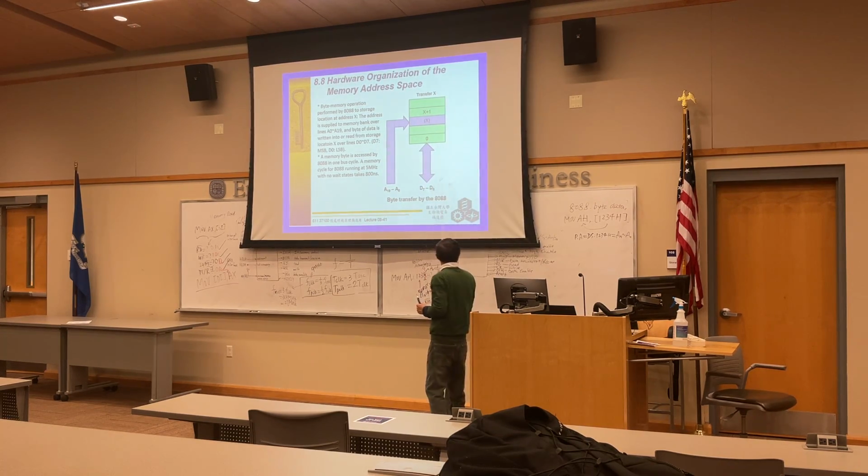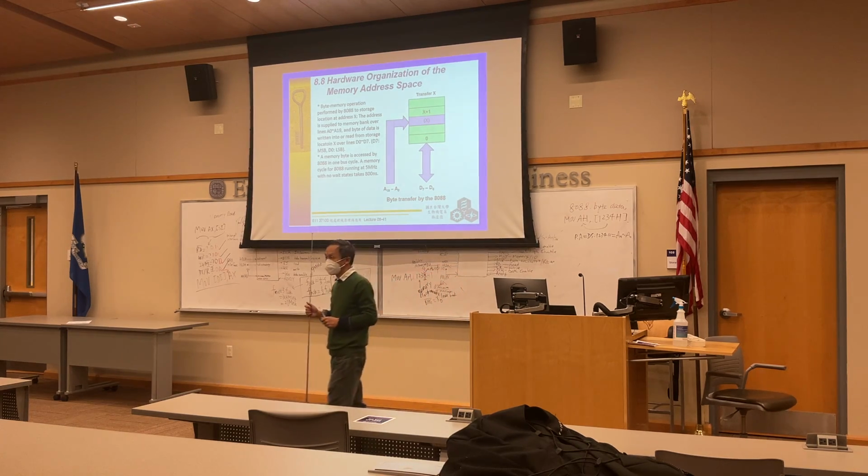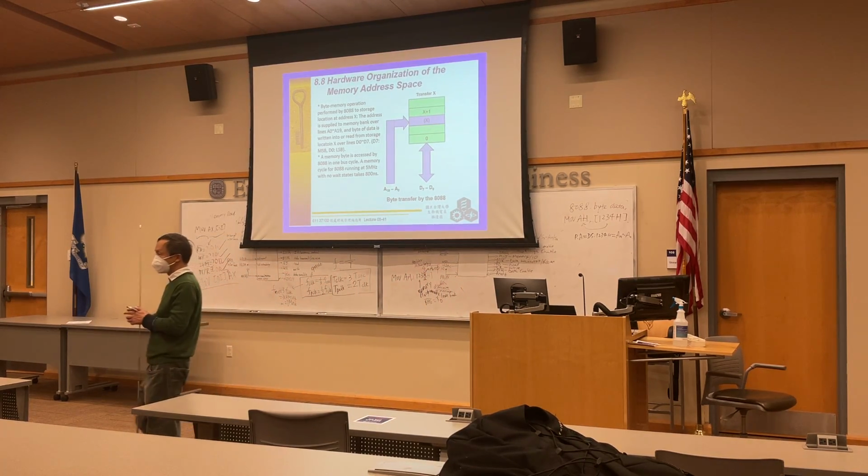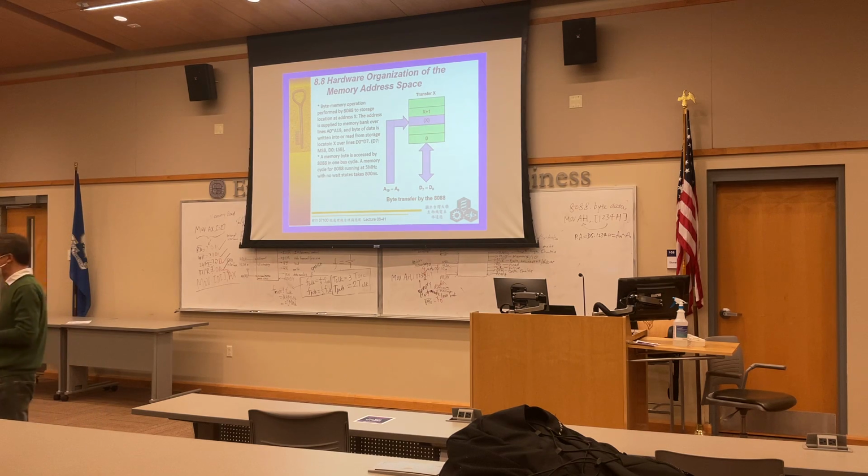From the data bus, it goes to the destination register. That's what's happening. The whole process can take multiple clock cycles, but only one bus cycle. Okay, easy. One bus cycle for a memory read or write of byte data on the 8088 microprocessor.